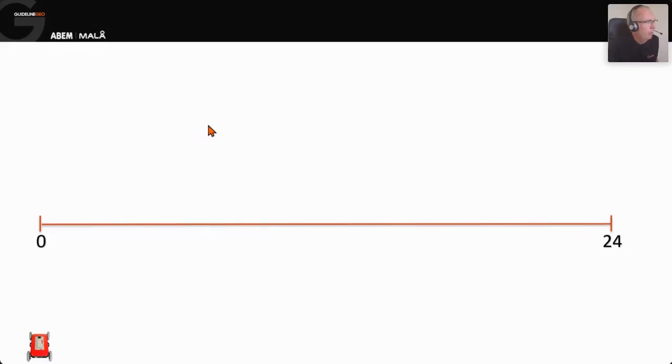We've got the GPR in the bottom left-hand corner. With the system, you can start the GPR on the baseline if you wish, you can cross the baseline like we're going to do now, or you can end on the baseline. But every profile, generally speaking, has to either start on the baseline, end on the baseline, or cross the baseline at some point. Your profile lengths can be different lengths if needed, but you've got to start, stop, or cross the baseline at some point to give that information.